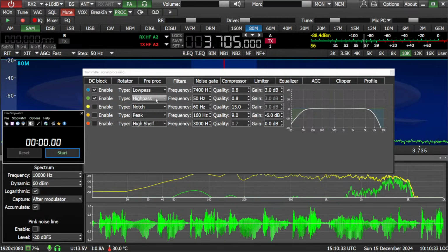And that's with a 200 watt carrier into a Kiwi SDR, which is 15 air miles away from me, on 3705. I hit that thing hard. So you'd see it splattering all over the place if it was splattering, and you won't. I'll show you. So I set my high and low pass filters. I stretch it out a little bit. Don't go below 50 hertz. I think this is a little bit of a stretch. I should probably change this to 60.